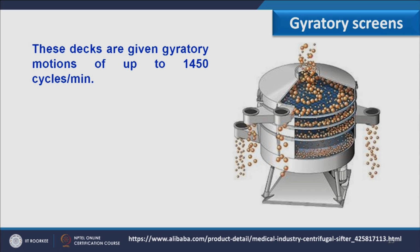These decks, which are available in a gyratory screen, have gyratory motion, and the motion is up to 1450 cycles per minute. So, here the cut view of the screen is shown, where we have the feed from the top, and due to this gyratory motion, I hope you understand what is gyratory motion. It is circular in one plane. So, gyratory motion takes place, and due to this the smaller particles will keep on falling, and the coarsest particles will be available at the top, and from the discharge spout the particles can be collected. So, as far as gyration is concerned, it has 1450 cycles per minute.